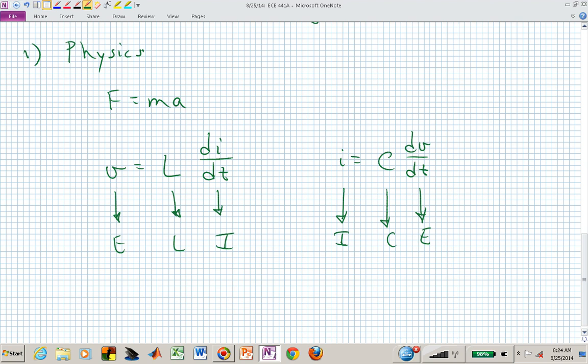So we will then look at a given system. Maybe it's an interconnected mass spring damper system. We'll have to figure out, how do we model that? How do we develop the differential equations to describe that? Or you might be given an electrical circuit, and using these fundamental relationships for R's, L's, and C's, we won't get too fancy. Maybe we'll have some op amps to give us some gains, etc. But now we have this system that we can describe either in transfer function form or in differential equation form, all based on the physics of that system.